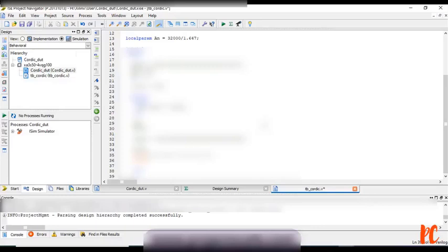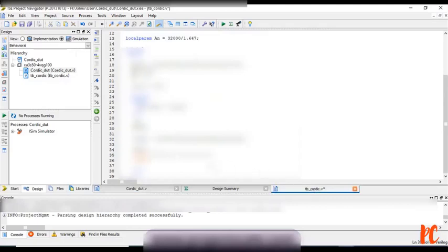Finally the CORDIC, what is the DUT module name we have given for CORDIC? We have given CORDIC underscore DUT, right? Since we are linking this with respect to DUT, I am copying this part. DUT, some instantiation name I am giving to be C1, followed by clock, cos underscore out, sine underscore out, x in, y in, and the last one, angle.